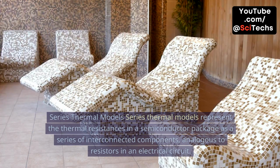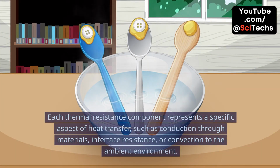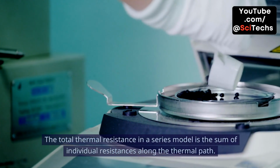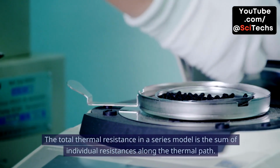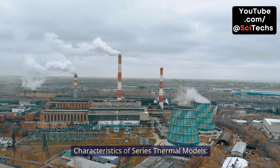Series thermal models. Series thermal models represent the thermal resistances in a semiconductor package as a series of interconnected components, analogous to resistors in an electrical circuit. Each thermal resistance component represents a specific aspect of heat transfer, such as conduction through materials, interface resistance, or convection to the ambient environment. The total thermal resistance in a series model is the sum of individual resistances along the thermal path.